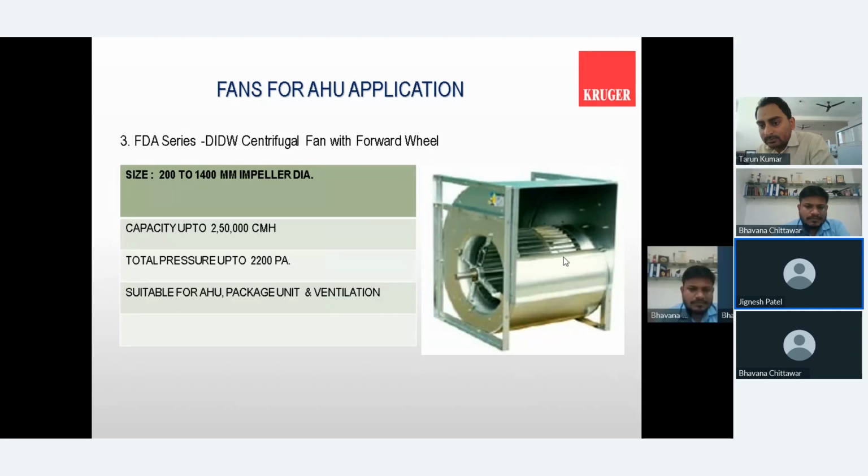So you mean to say that if I rotate a backward direction fan in the forward direction, what will it do then? Will it do reverse suction? Reverse suction, yes sir. That's why when going for approval, we always confirm from the client whether it is counterclockwise or clockwise. So protection also has to be taken care of so that it does not rotate in the reverse direction.